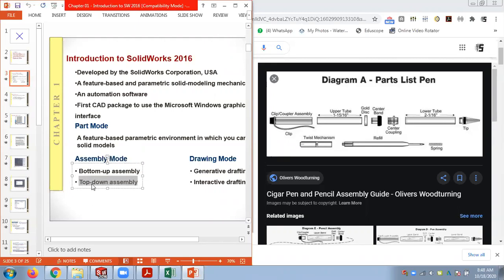So what happens in the bottom-up assembly is normally if you don't consider the measurements critically when you try to assemble this, there will be problems, there will be interferences, it's not matching, sizes are not fitting with each other. There are problems in bottom-up techniques if you don't care about the measurements critically. But in the top-down method, what we do is we draw this one in the assembly mode directly, we don't draw separate parts. And we draw this part on top of this. While assembling, we develop the things.